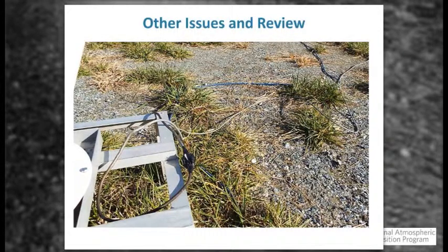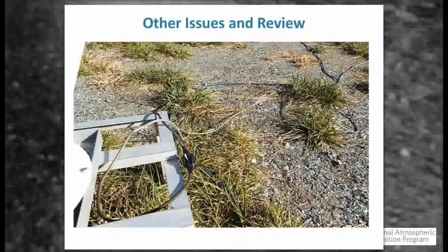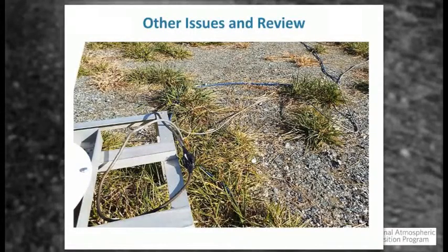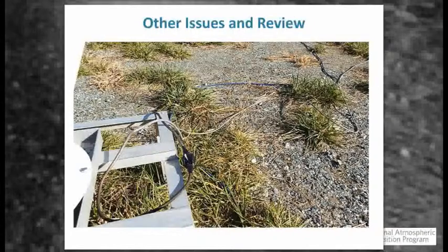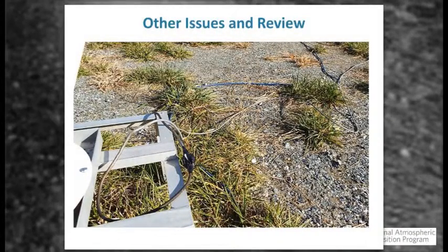Make sure it's sized properly. Make sure all your connections are good. The little bundle of electrical tape there isn't going to cut it. Get a little moisture in there, it's just going to leak power, and that's not going to work well. Most of what we recommend is, if you don't have the capability of putting it below ground, try to put it in conduit to keep it dry and away from the rodents munching on it. Rodents love to munch on wiring.